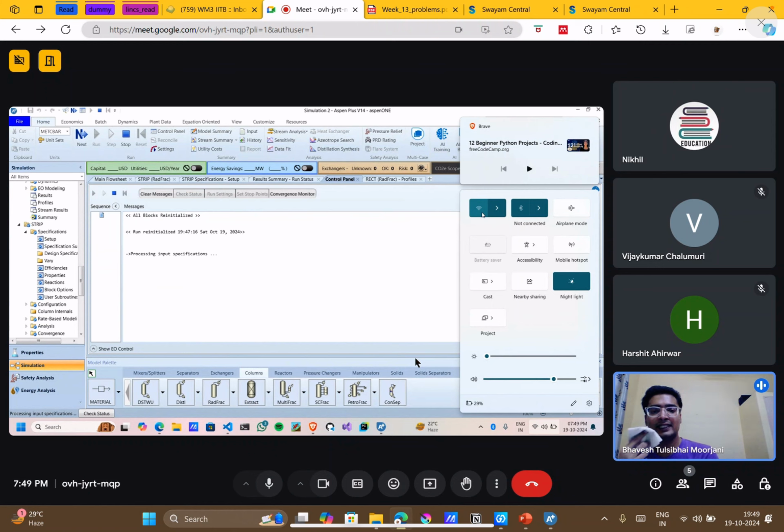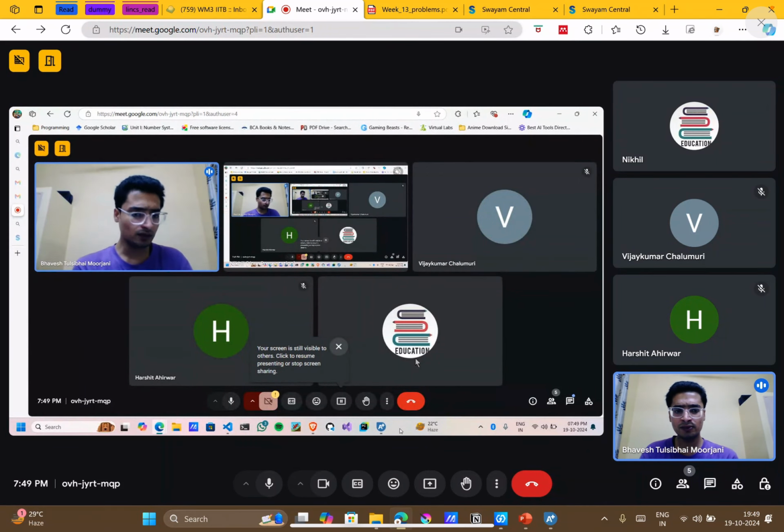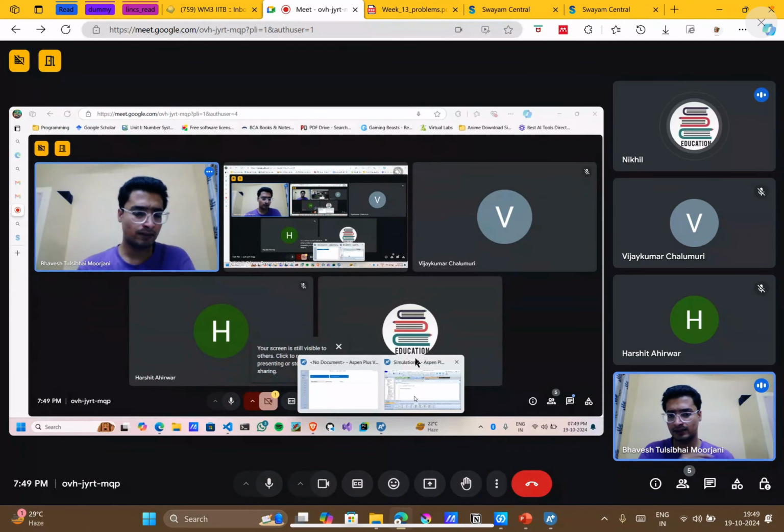So clearly there is a difference. Because of that, you are getting this error that the feed is below the pressure of the column. We can rectify it by changing the pressure of the prior column, and that should give you a better answer.